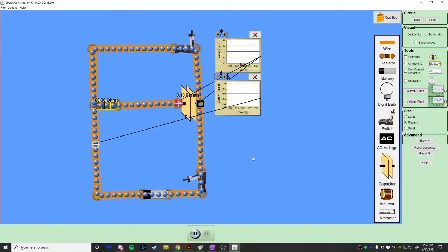What's the answer, though? This is extremely simple. You take the resistance, you multiply by the capacitance. What's the answer? 10. 10 seconds, right? It should take 10 seconds for this thing to do what? What does that mean? What does the 10 seconds represent? Yeah, but how much charge is going to be on the capacitor after 10 seconds? So 63%, right? So about how long is it going to take to be fully charged?